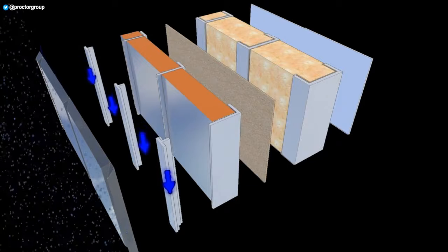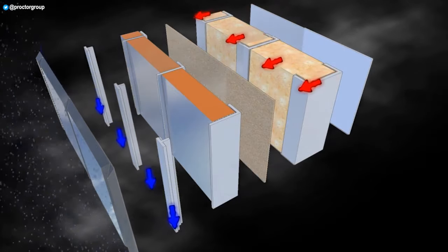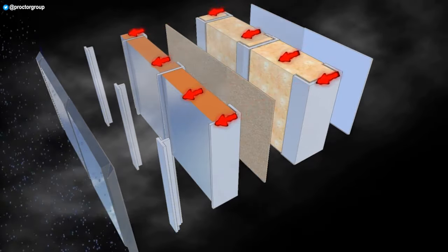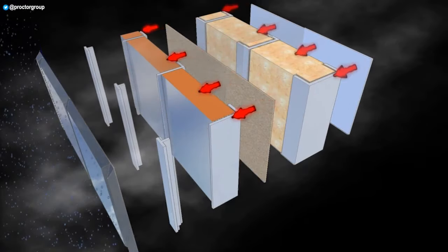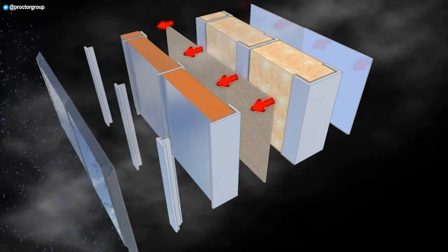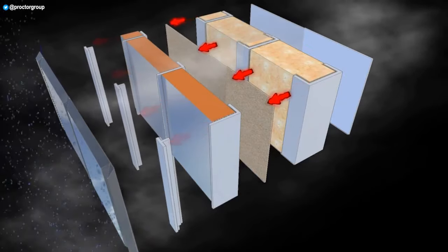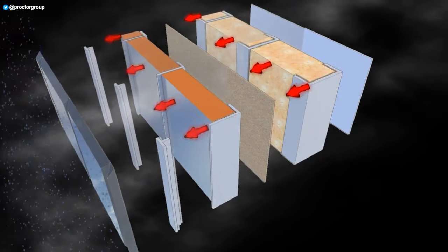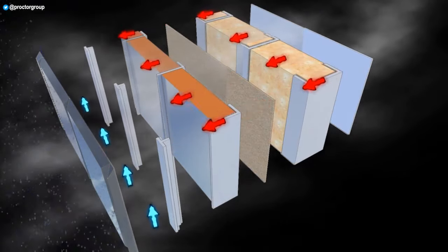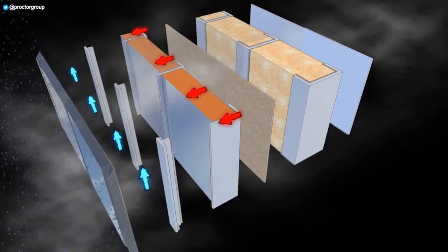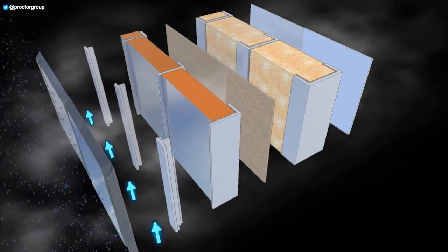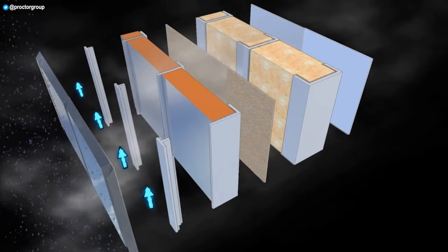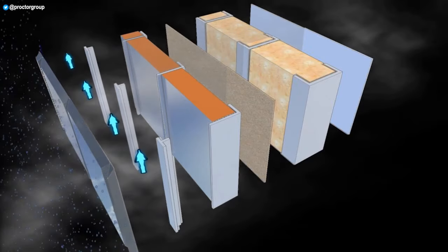As well as for allowing for the drainage of liquid water, rain screens should be designed to ensure moisture from the interior of the building can escape and that any wetting associated with water ingress through the outer rain screen can dry out. This is typically achieved by fully ventilating the void between the outer cladding panels and the inner leaves of the wall. By ventilating, we ensure moisture vapour from all sources can escape freely to the outside.